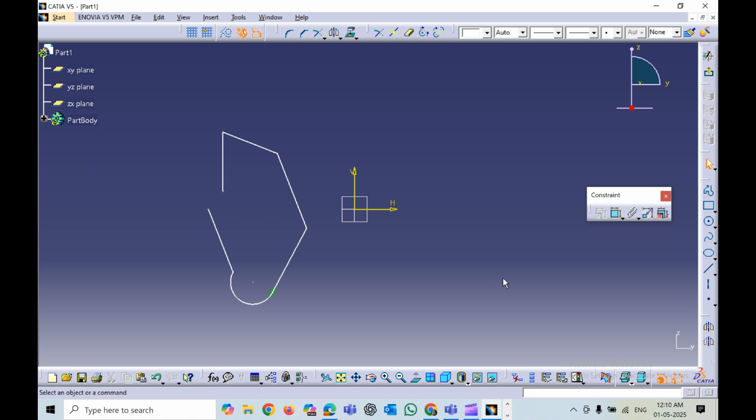So when it comes to constraint, we have two types of constraints. One is a constraint defined in dialog box. The other one is the formal constraint. So we are going to look into both the things. So first, constraint is nothing but applying the dimensions. So let me apply a dimension for this one. So this is the dimension, which is 47.471 in mm.